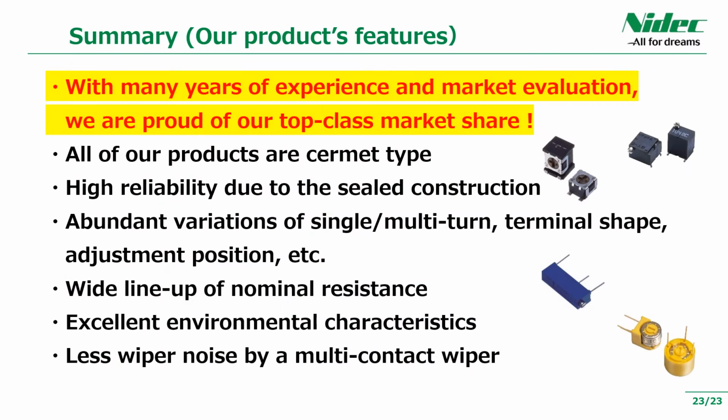Please see the summary at the end. The biggest feature is that it has been evaluated by the market for many years and has a top-class market share. In addition, all of our trimmer potentiometers are cermet type, and they have sealed structures and are highly reliable. There are a wide variety of products, and you can select the most optimum product by selecting the rotation speed, size, terminal shape, and so on in accordance with the intended use. There is a wide range of nominal resistance values and each owns excellent environmental characteristics. We have also taken measures to reduce wiper noise.